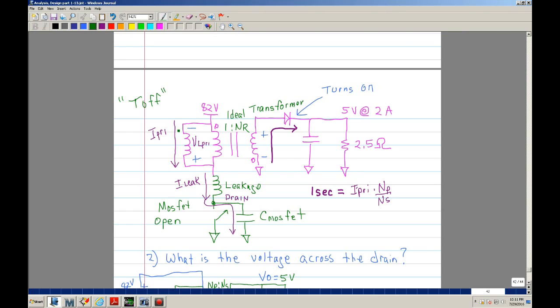But this current that is flowing through the primary, because this is coupled to the secondary, okay, this current, or the energy that is through the primary, or rather the gap, then is allowed to transfer to the secondary. Okay, and during that time, the signs on the primary change. This was positive, now they flip because of Lenz's law. Now you have negative and you have positive. So you have a negative on the dotted, that means you're going to have a negative right there as well, and a positive. And if you have a positive, this turns on, so basically you have a short.